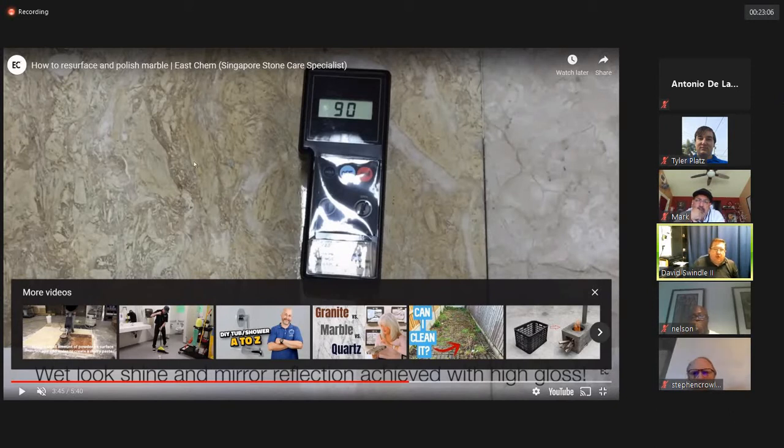As we talked about with concrete, if the concrete is soft, we use hard diamonds. If it is hard, we use soft diamonds. With marble, because it's a softer stone, we'll use a harder set of diamonds. Granite is a much harder stone, so we use soft diamonds for that. When we talk about hard or soft diamonds, we're talking about the metal or resin that holds the diamond onto the tooling. Okay, so generally speaking, this is the process of dealing with these floors.